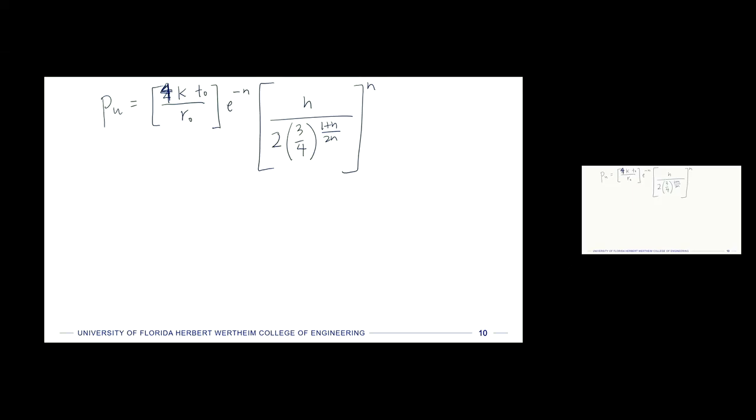So this is an expression that we've derived for this pressure. If we keep pumping up the pressure vessel, it's going to experience a plastic instability and basically burst. So we had before our T naught was equal to 1/8 of an inch. R naught was equal to 9 inches. And now we don't care what the yield stress is because we assume that this has already yielded. We're not using that anymore. What we need now is the strength coefficient, K, and the power coefficient from the strain hardening curves.